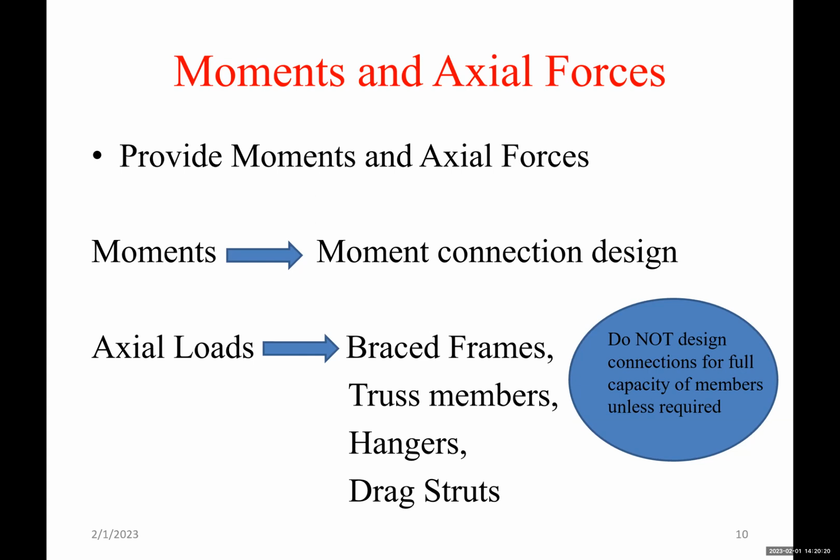So if we have a combination of moment, axial, and shear, we have to include that. Moments are for moment connection design, for example, moment frames or cantilevers. Axial loads are in braced frames, in truss members, in hangers, in drag struts. All these need to be designed for.